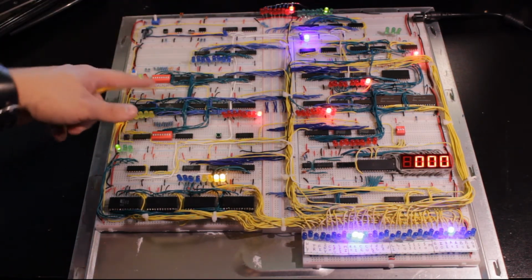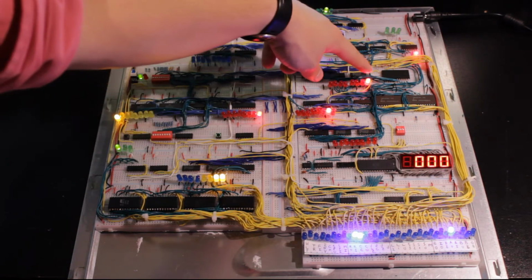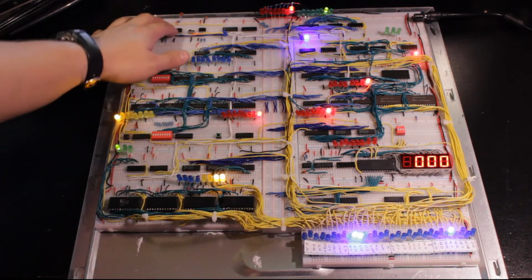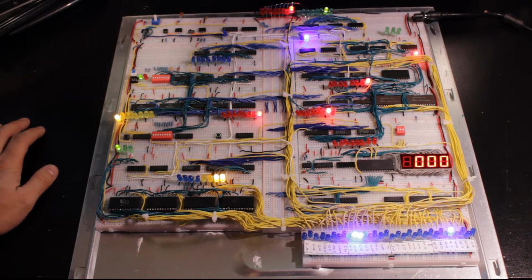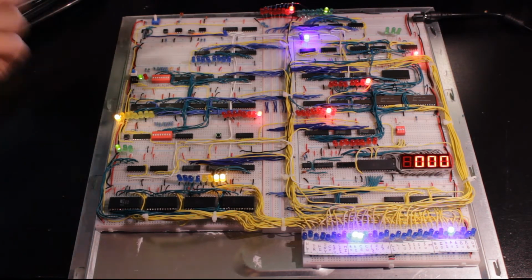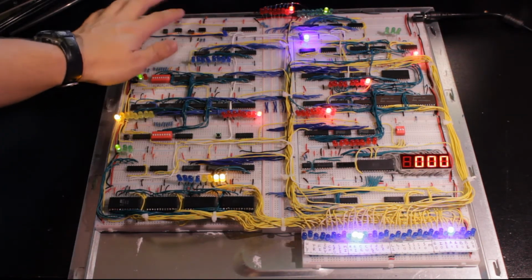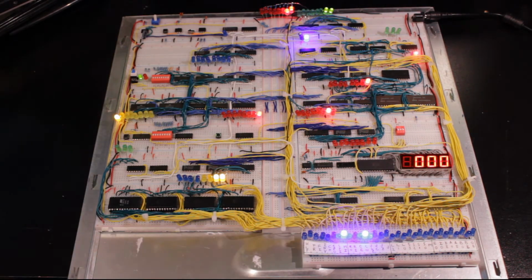And now we're looking at the location 0x80 in memory, and we're going to put the value 1 from the A register into that, and then we're going to early terminate. You can see that already happened because I have it on the negative clock edge, sorry, the positive clock edge, but it's level sensitive to the clock and it triggers on that one. Then the early terminate is the next instruction, and we're back to a fetch cycle for the next action.